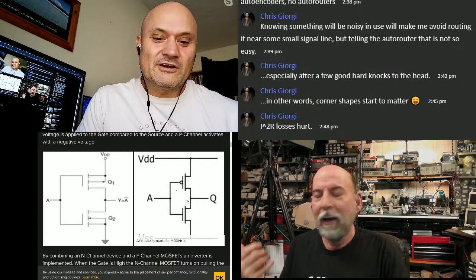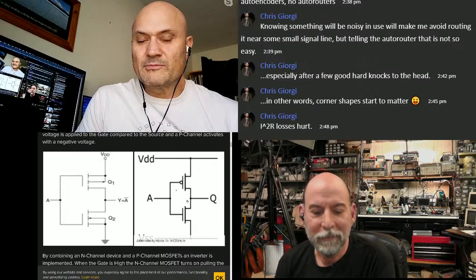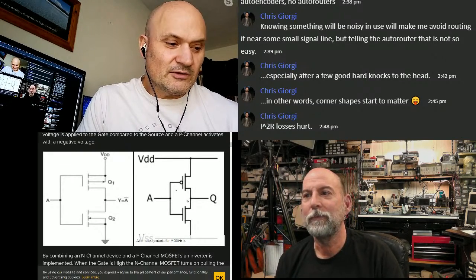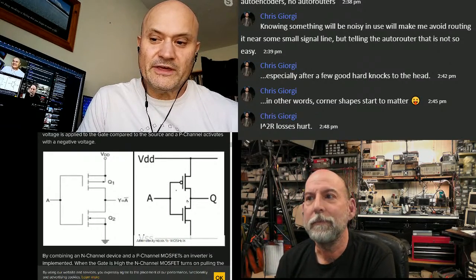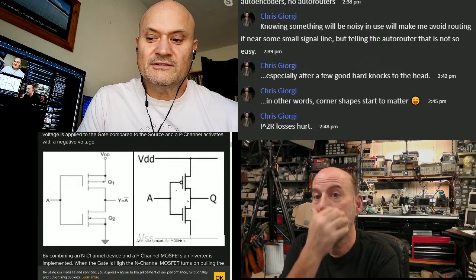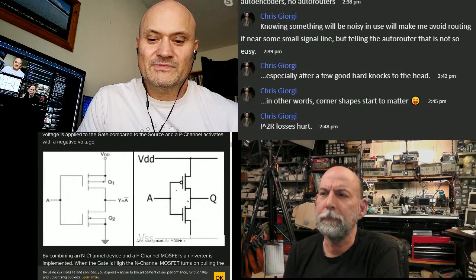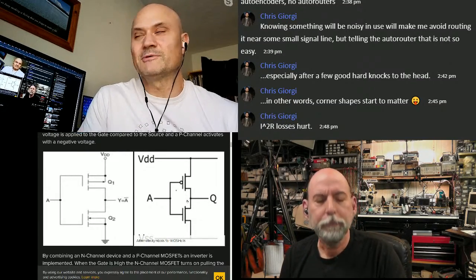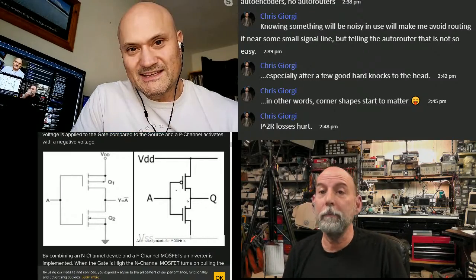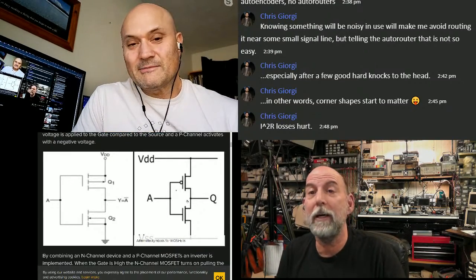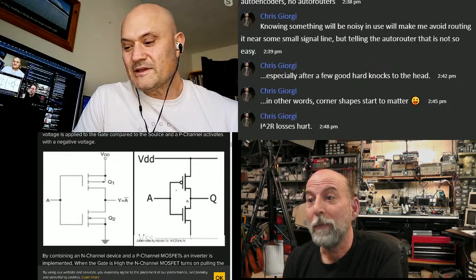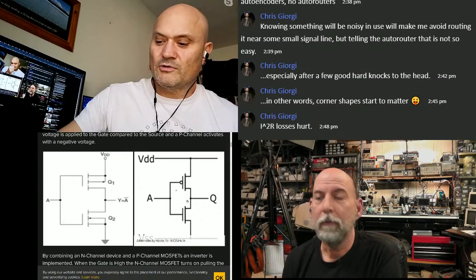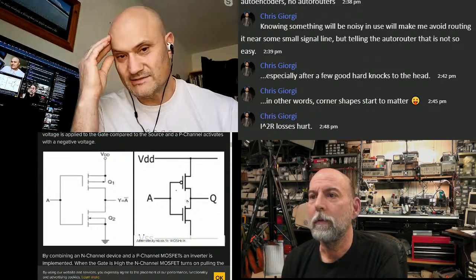And it's little wonder why motherboard manufacturers quite some time ago already went to 2 ounce copper on the inner plane layers. 2 ounce or 2 mil? Sorry, 2 ounce. 2 mil would be crazy. Well, but at 100 amps, some of them are going to go to 4 ounce, or are already using 4 ounce planes.